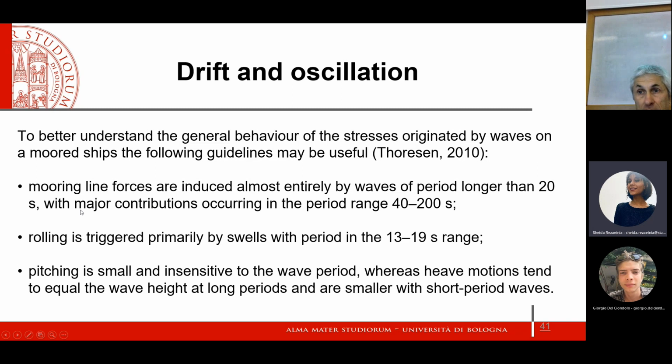Some additional orders of magnitude. Mooring line forces are induced almost entirely by waves of period longer than 20 seconds, because 20 seconds is the order of magnitude of the forcing needed to fully stretch the mooring lines.